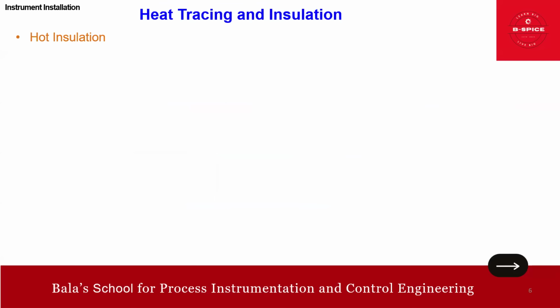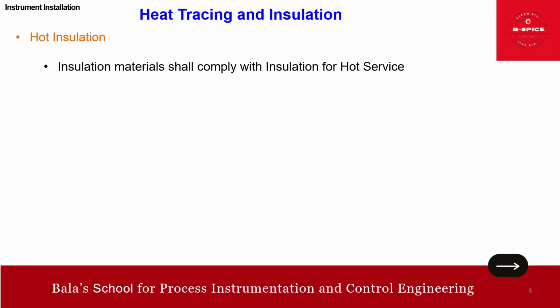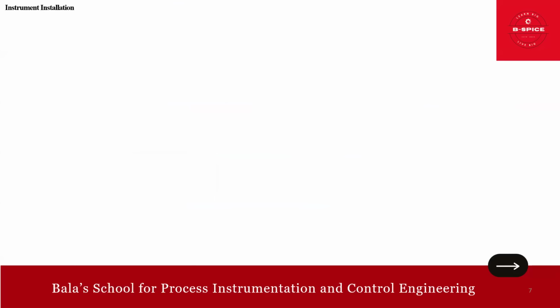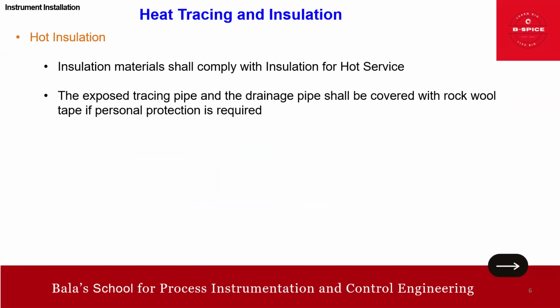Then there is also one topic called hot insulation. For this insulation material, we should comply with the insulation for the hot service. The exposed tracing pipe and the drainage pipe shall be covered with rock wool tape if personal protection is needed. Of course, this is not much for us, so I just covered only the main points.